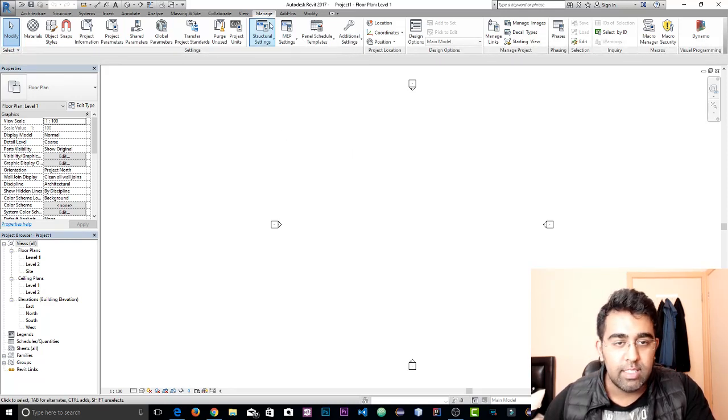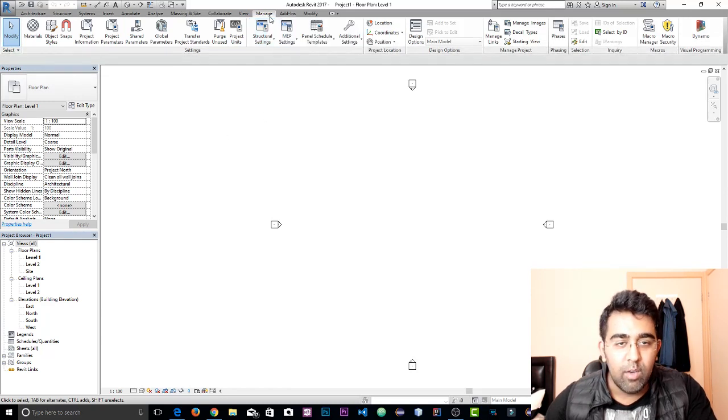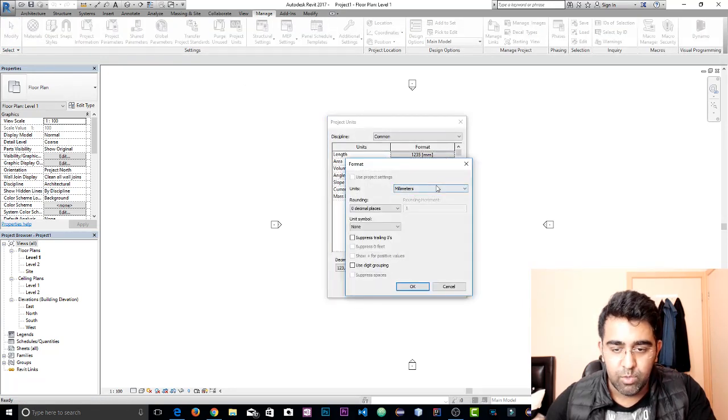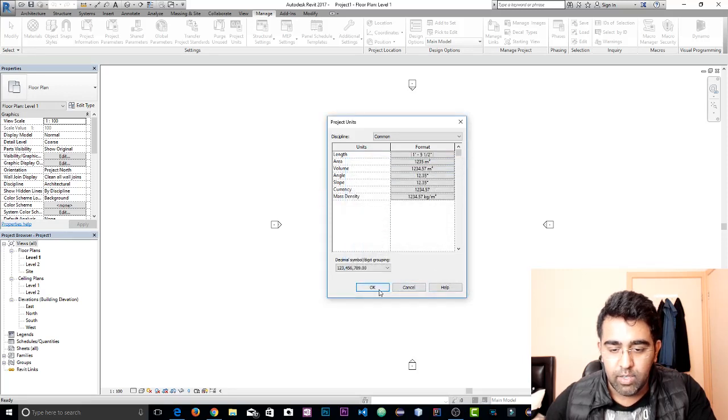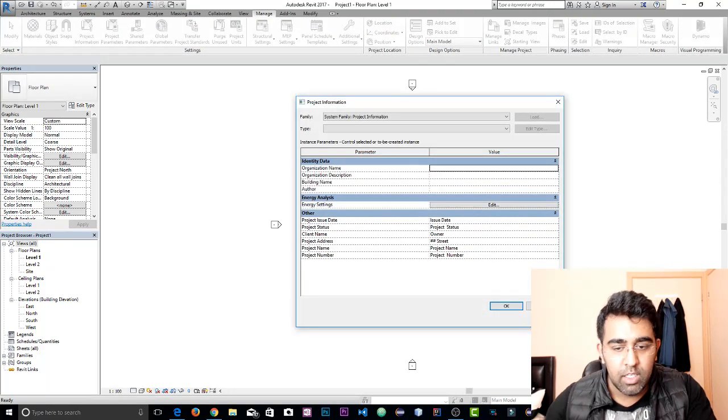I've got my webcam there, but I've got my live stream messages going on the right screen. Now when you go to the Manage tab, we will click on Project Units. I prefer to work in feet and fractional inches. Let's click OK, click OK, and then I will put in some information for my project.